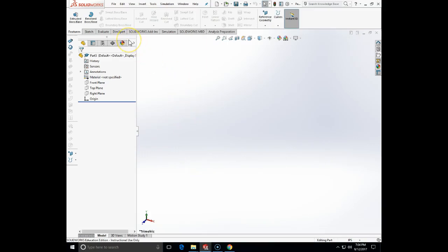Alright, in this exercise we will get introduced to the mold making workflow in SolidWorks, and we are going to make a simple two-piece mold, so the cavity and core mold for making a part. It is very important that we have an object with drafts, and for our casting purposes and for the surface roughness of the 3D printed part I will go with a minimum of 5 degrees of draft angle.